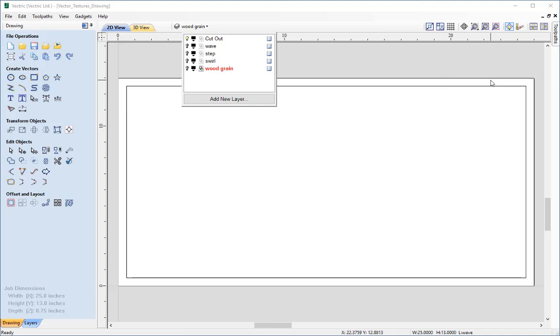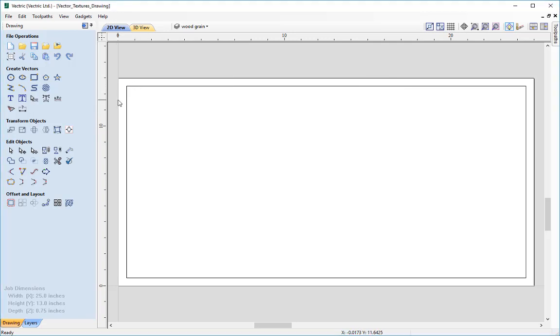or where we're going to actually use the cutout for the tile. So to accomplish this, what we do is we create the vector texture larger than the panel that we actually want to create, and then we create a cutout pass which is smaller than the textures. So then we get a full cut effect from the tool when any of the vectors go inside and outside of that tile boundary.